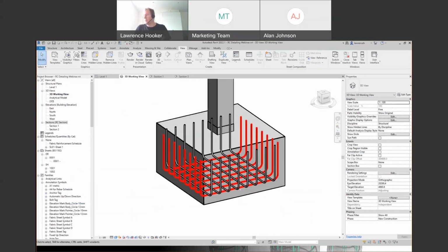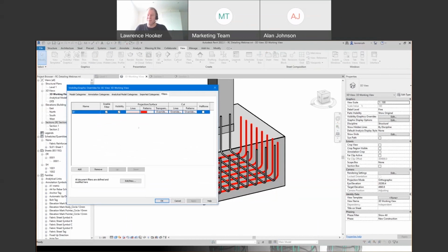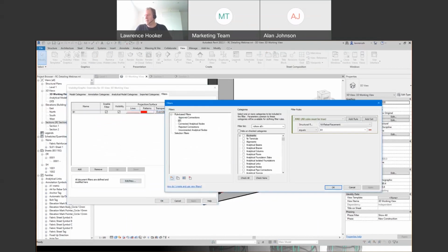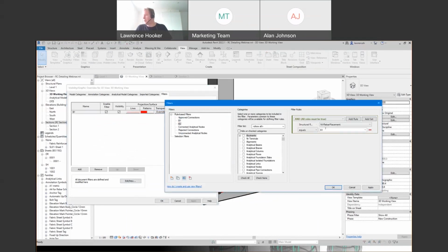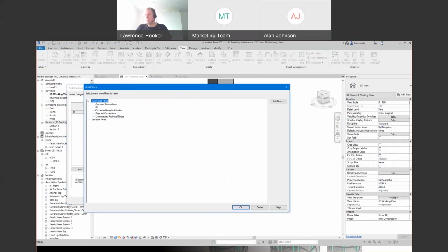Now, what's quite nice is if you want to now do a B2 layer, which of course we will do, I can just go to edit and new, select that filter, duplicate it, which is nice and easy, rename that in here. That's obviously now going to be B2 in this example. And then of course, I just need to change the parameter to be equal to B2. Okay, we can then add that filter in just in the same way in here, like so.